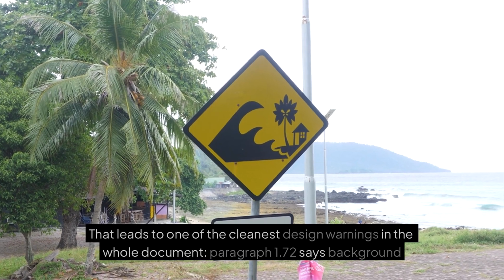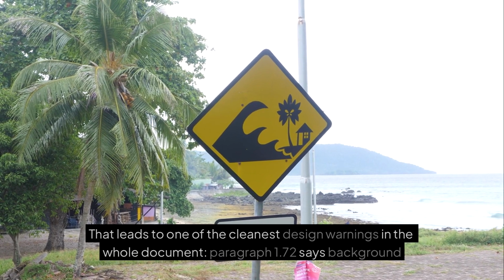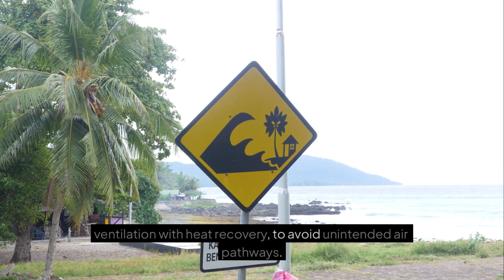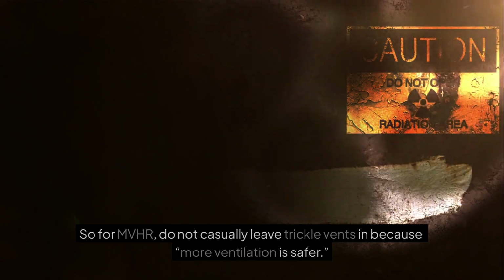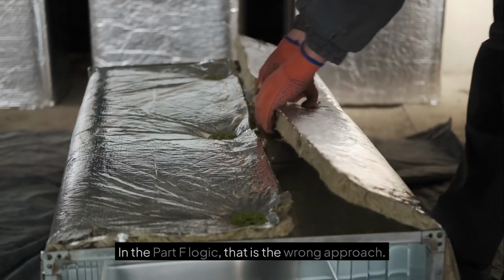That leads to one of the cleanest design warnings in the whole document. Paragraph 1.72 says background ventilators should not be installed with mechanical ventilation with heat recovery to avoid unintended air pathways. So for MVHR, do not casually leave trickle vents in because more ventilation is safer. In the Part F logic, that is the wrong approach.